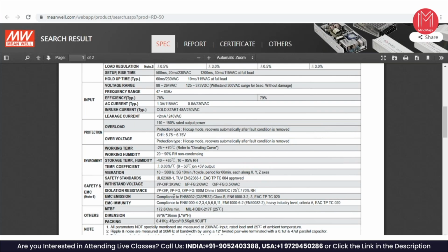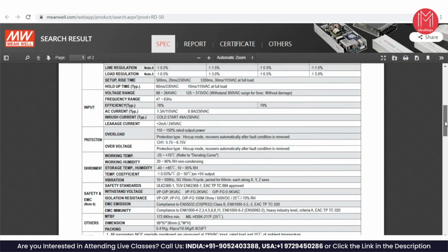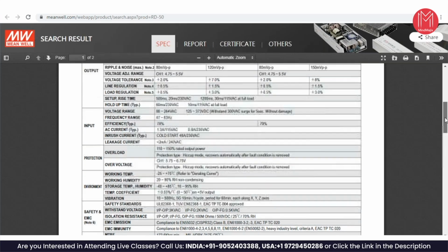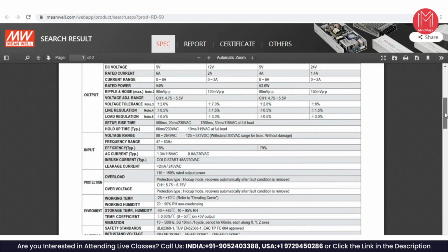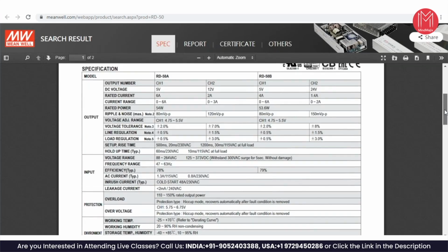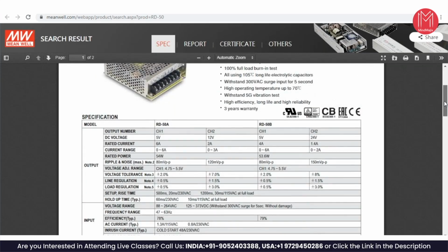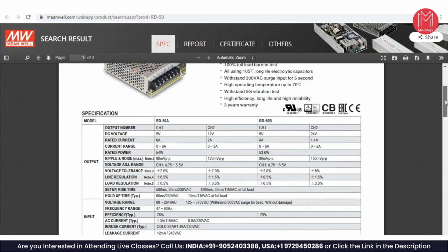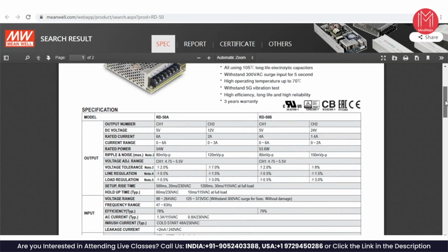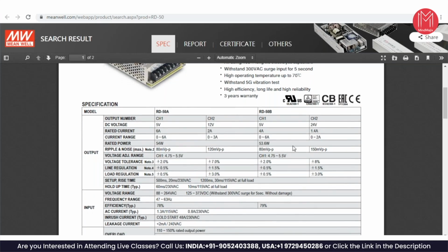And a failure can be anything, some vibration. They didn't give a power factor specification, but that's also an important specification, power factor, for the mains usage. If you have 98%, you don't have to really have 98% power factor. But if you have a 60% power factor, you're drawing more current. But from the mains, you don't really worry about this level so much.